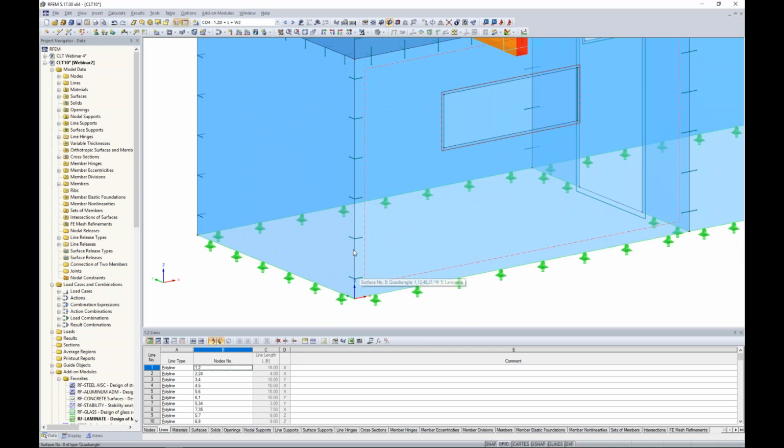So when I zoom in here to the line hinge location of these two panels, what I see is hinges on both sides. Now, with any finite element software, whether it's RFEM or anything else, we know that if we have two beam members framing in at a joint, and those are the only two beam members that exist, and we set the end rotation of these beams to be released for moment, we're going to get an instability. You never want to set both beams in that case to pin. You want to leave at least one fully fixed. Otherwise, we get instabilities and we can have issues within the program.